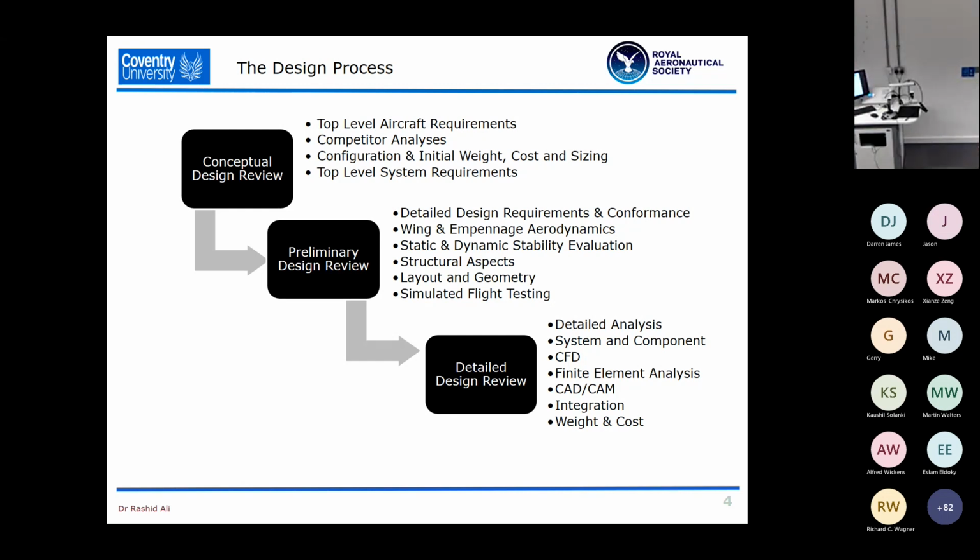Now, aircraft design is a very iterative process. For example, I always say to all my students who cross my path, aircraft design is a very complex subject. It has one design variable, and that's weight. And as you'll see in some of the slides later, practically everything we do is a function of weight. Whether it is takeoff performance, glide performance, the Breguet range equation, or turning performance, everything basically gets down to the weight. Even drag is a function of weight as well. So that's very, very important.